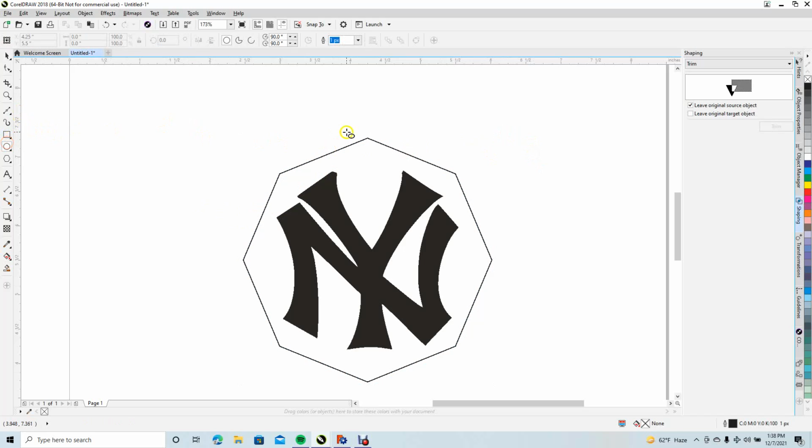Now we're going to drag our circle tool right from the node there, and we're going to create a little, maybe 0.5 radius. And then we're going to go ahead and get the circle tool again. We're going to create 0.25 roughly. Okay, now we're going to go select that. We're going to change trimming here on the shape tool to weld. We're going to weld it to here. And then we're going to go ahead and select that. I'm going to change it to trim. Then we're going to trim away. Okay, that just got rid of the center piece there, so we're going to hit delete.